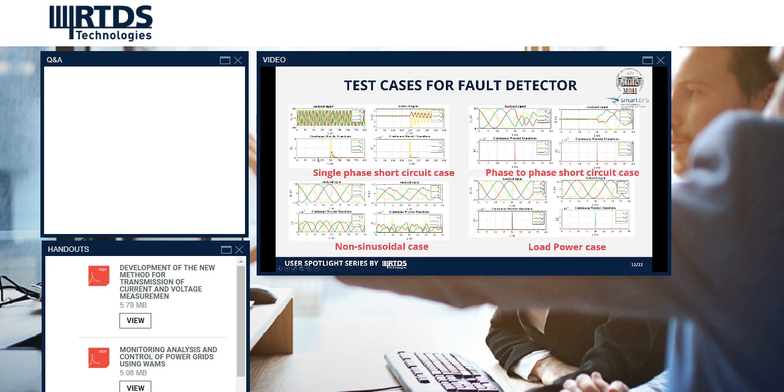Depending on the type and the location of the short circuit, different times of the wavelet function maximum were obtained. The short circuit time selection algorithm determines the minimum time to reach the maximum of the wavelet transform function for each phase of current and voltage.